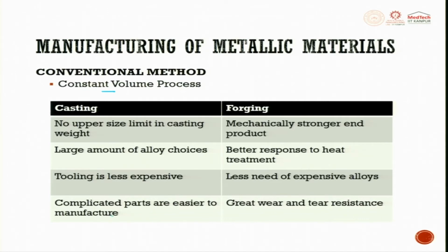But if you want mass production of the same thing, we try to avoid casting, because every time, collapsing and making the mold becomes a challenge. Predominantly it is used for complex shapes. For large parts, casting comes up in a big way.